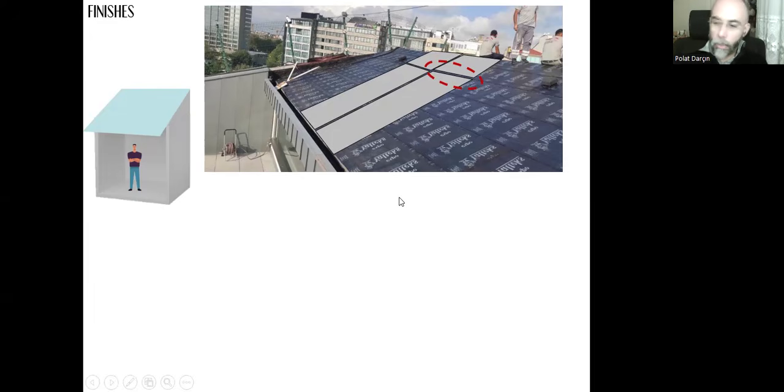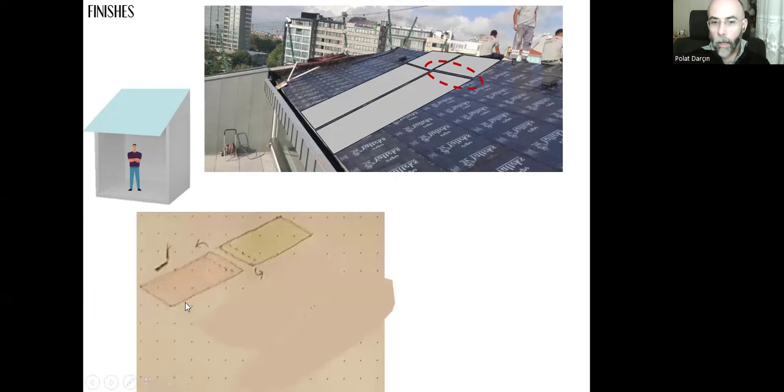Let's take a look at this combination. We can use a specially produced interlocking method to combine two sheets together. This horizontal joint can be created like this. First, we need to fold the sides of each panel like this. This one will be folded like that. The upper one will be folded like this, creating some sort of hook like that.